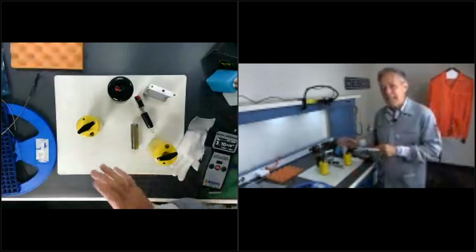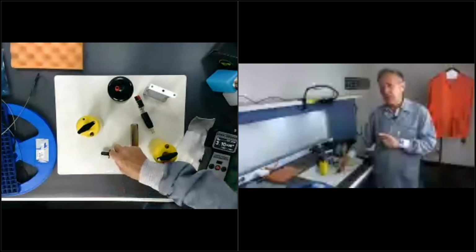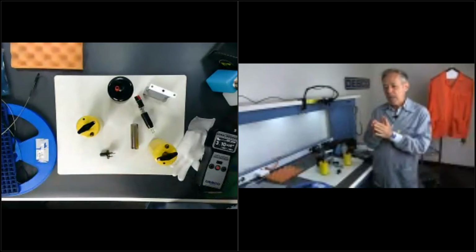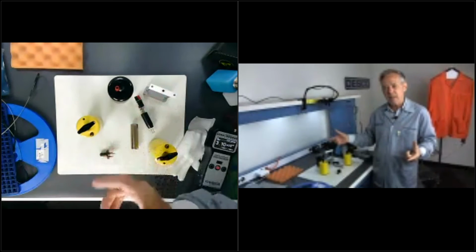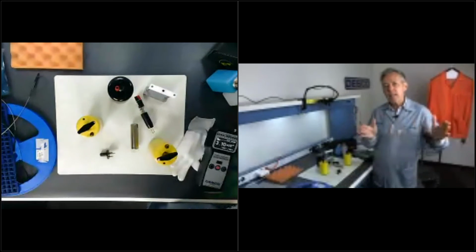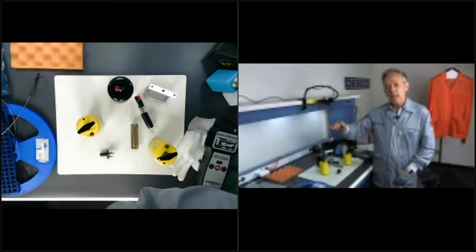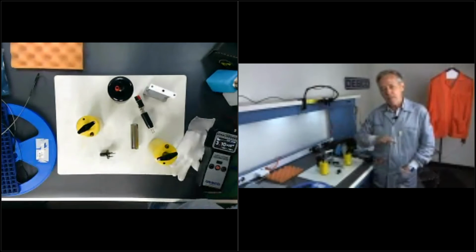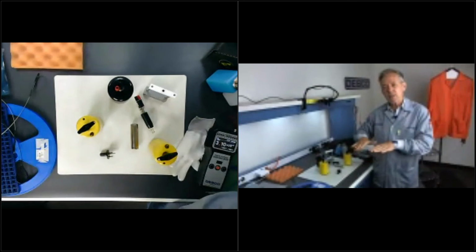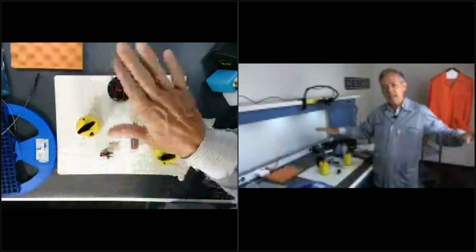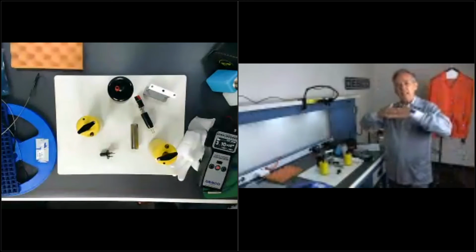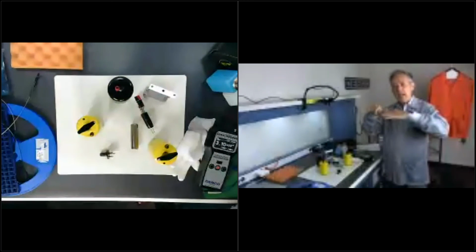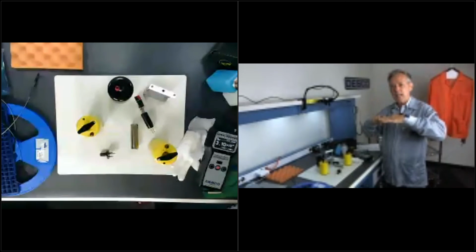Okay, when I mentioned tile to tile, and I'm saying not conductivity but connectivity, I want to make sure that if I have an individual tile type floor, like 12-inch tiles or 24-inch tiles, each one of those tiles is bonded together electrically. The way we do that is with the conductive adhesive underneath. Once I ground that adhesive with that copper strip in there, and stick those tiles down to it, that's what attaches tile to tile to tile. The same thing with my snap-together floor: once I snap those tiles together and interlock them, each tile is making electrical connection between tiles.